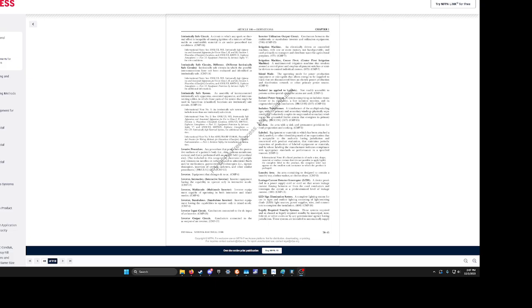For example, Underwriters Laboratories, UL, you're going to see that on basically every receptacle outlet, every switch, maybe light bulbs, I'm not sure on that one. But if you don't see it on there, and you don't see a label from another company that is considered within parity of UL, do not use that product, as it's either a knockoff or it's made illegally, which, I mean, at that point it's splitting hairs, but, point still stands. You need to have your UL label.